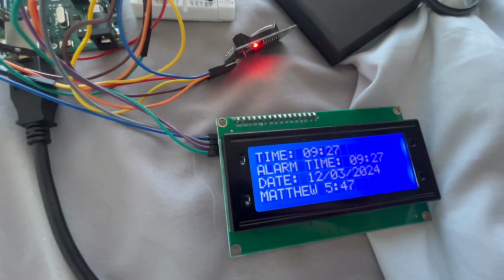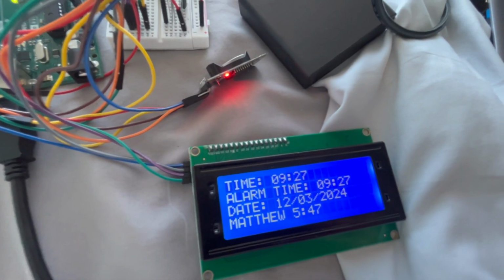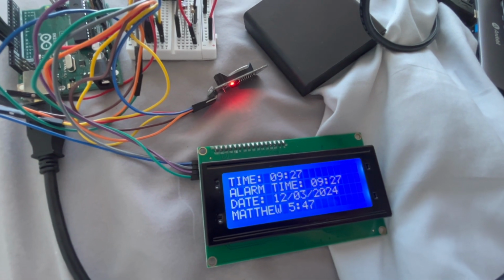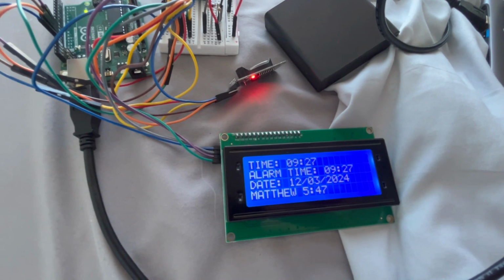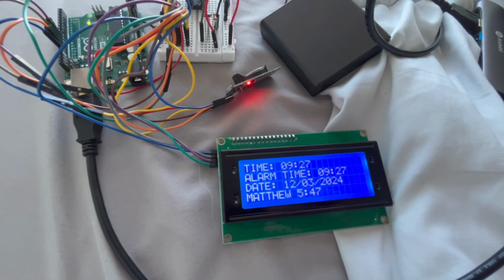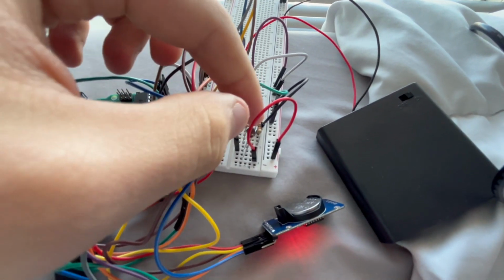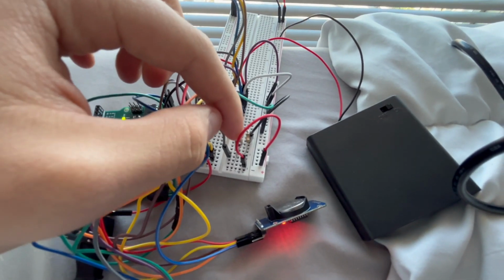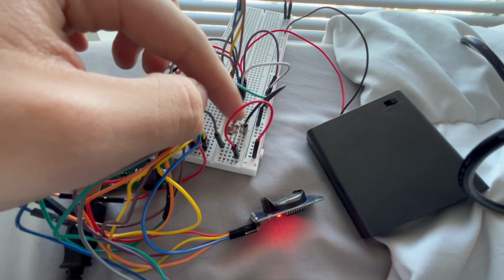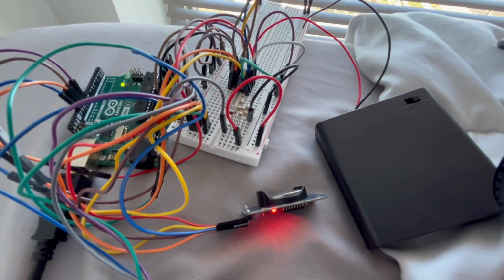And then I have this LCD display, which acts as sort of its own processing. So if I go to sleep, I close my laptop, I can still have sort of a functioning alarm clock. So it's not really that useful for this project, but outside of this project, like outside of the grading purposes, it is helpful. I also have this photoresistor here, which is wired in a voltage divider for max resistivity. It has a nominal resistance of 15 kilo ohms, and so that's what I got through this little series of resistors.